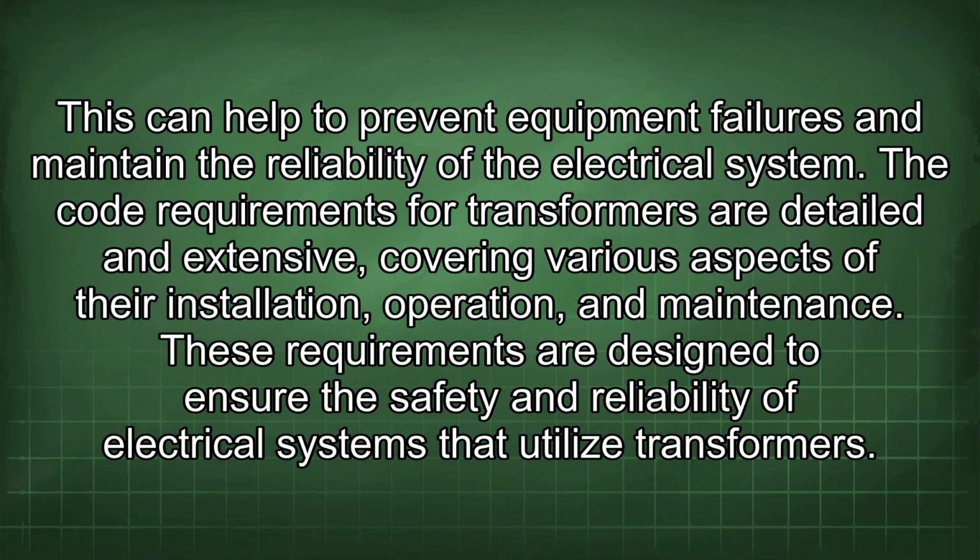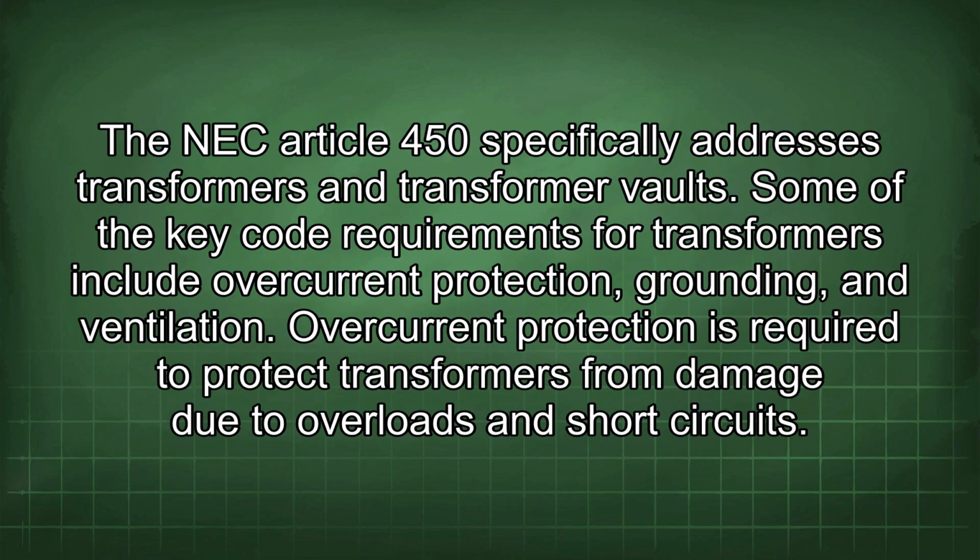The code requirements for transformers are detailed and extensive, covering various aspects of their installation, operation, and maintenance. These requirements are designed to ensure the safety and reliability of electrical systems that utilize transformers. The NEC Article 450 specifically addresses transformers and transformer vaults. Some of the key code requirements for transformers include overcurrent protection, grounding, and ventilation.